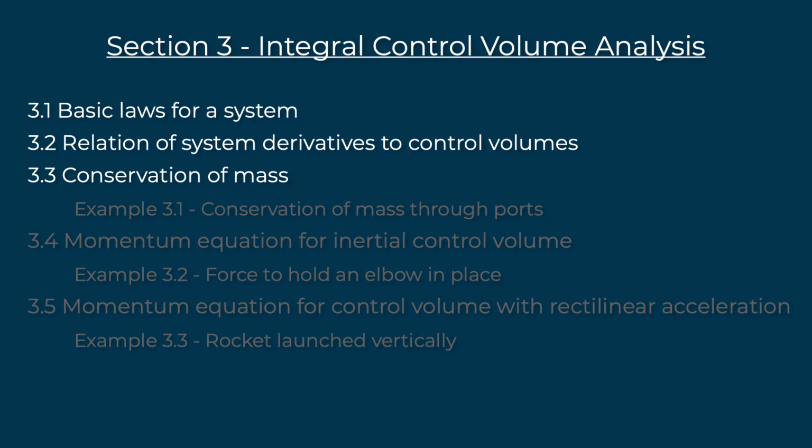something we want to know what the forces are on it. Okay, so in this lecture we went through the equations, we talked about how the laws apply to matter, right? And when we look at a control volume, the only thing we really need to do is talk about balancing the rate of change within the control volume with all the different quantities that can enter or leave a control volume. Okay, that was like the bucket example. So the amount of water in the bucket can change as a function of how much is flowing in or out of this bucket. So we looked at all the equations, different ways to simplify them, how we can have very simplified forms if it's incompressible or uniform velocity, and that's a much easier way to solve problems instead of the integration form.